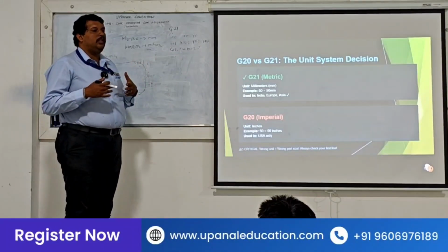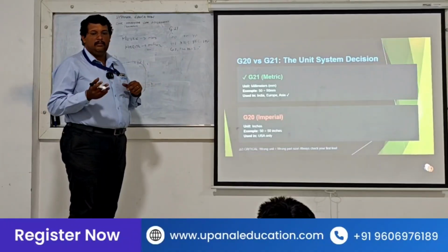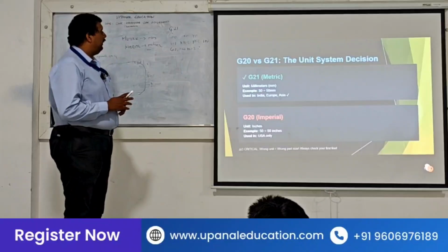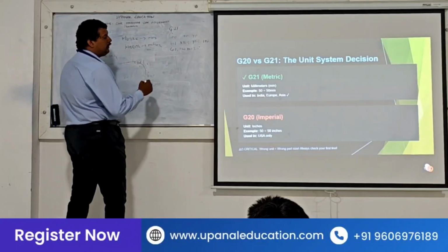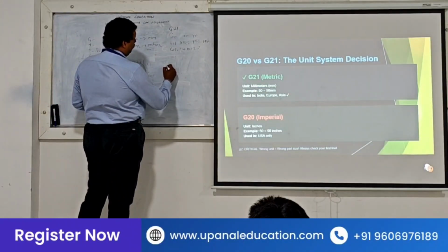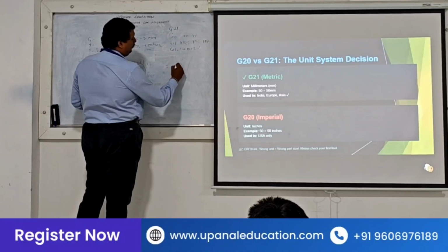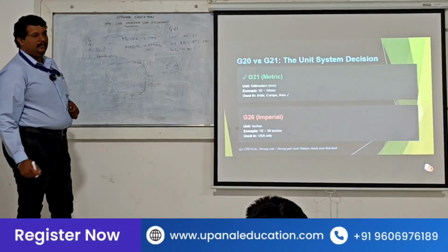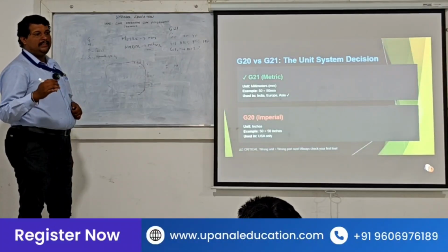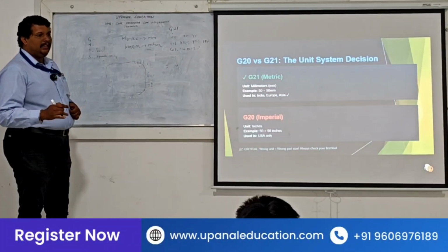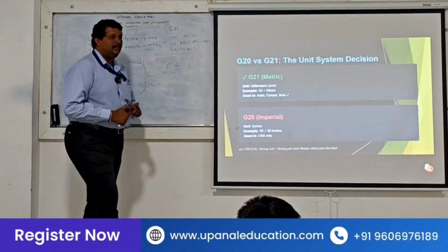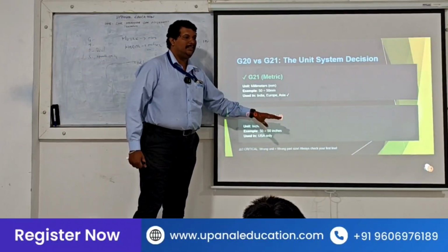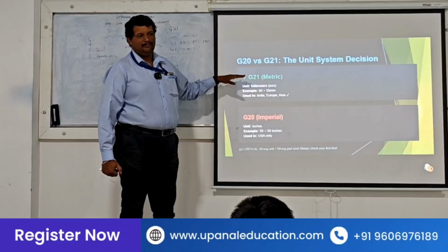When you are getting confused about whether G20 is inches or mm, since they are so close, remember ABCD. Which comes first, I or M? A, B, C, D, E, F, G, H, I. I comes first. So always remember, first comes G20. 20 will be inches and 21 will be mm.